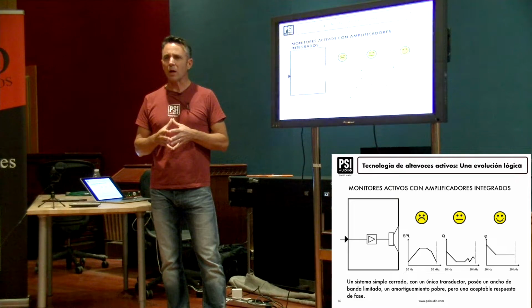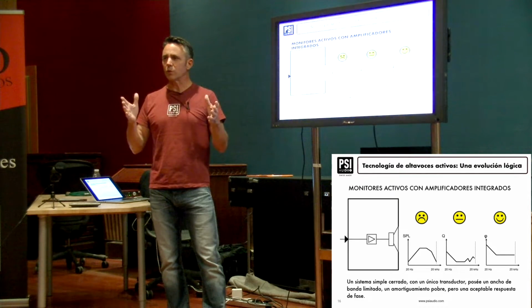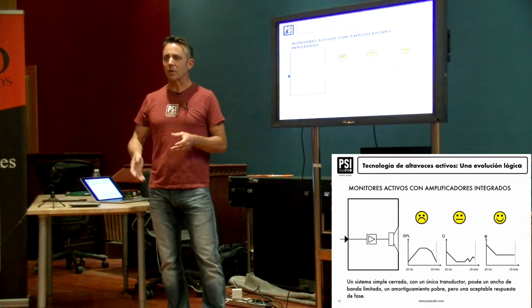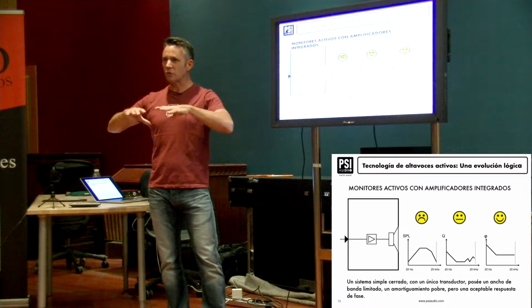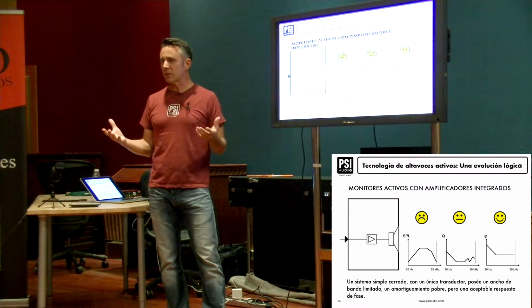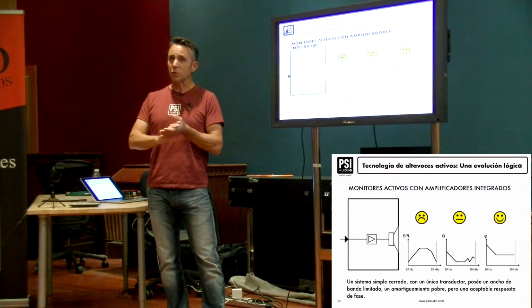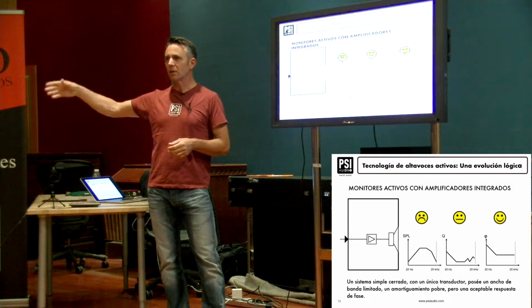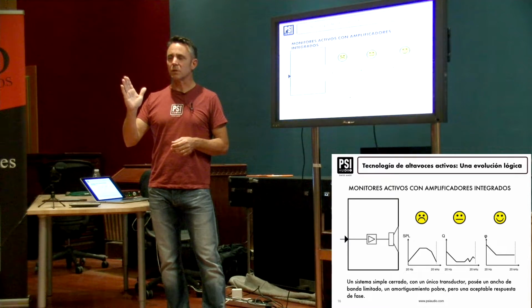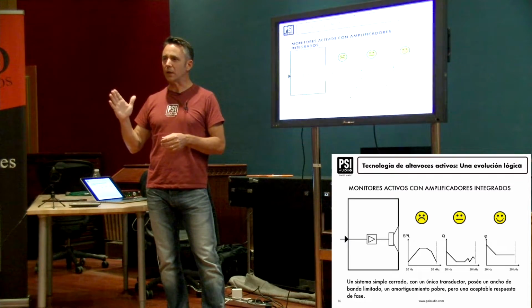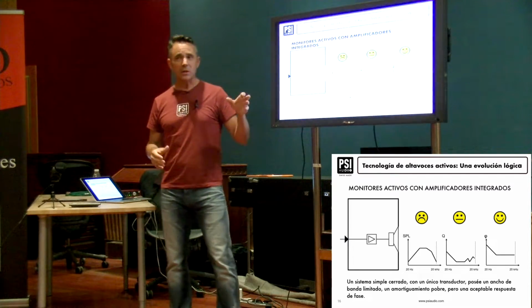But basically, when you have high frequencies and low frequencies all together that leave, like in a snare drum, that'll go "ta". The high and low frequencies will all leave the drum at the same time and reach your ear at the same time. Unfortunately, any type of signal that goes through any type of filter will be affected, and the low frequencies will be slowed down compared to the high frequencies. So if you go through any type of filter from a "ta", you'll end up with something that's more like "t-a", where the low frequencies of the "a" are delayed compared to the high frequencies of the "t". So this is important to keep in mind.